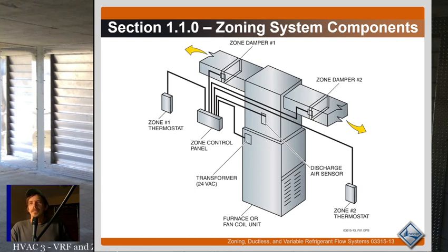The other way you can approach it, besides having a bypass, is to have a communicating system with a variable speed fan, in which case the zoning system operates a lot more like a commercial VAV system. So a commercial VAV system, all your modern ones anyway, the older ones had bypass dampers and everything just like a residential system did. But a commercial VAV system, you modulate the airflow through a VFD on the supply fan. With the residential one, it'll be an electronically controlled variable speed fan. And as the zones close, they communicate back to the system that they are closing, so that the system will drop airflow and drop the capacity of the outdoor unit. So those are really the best options when it comes to residential zoning.